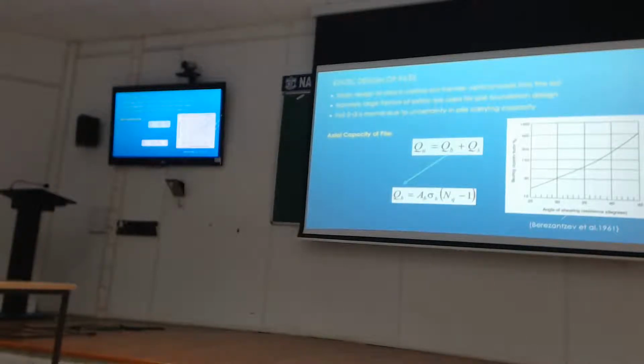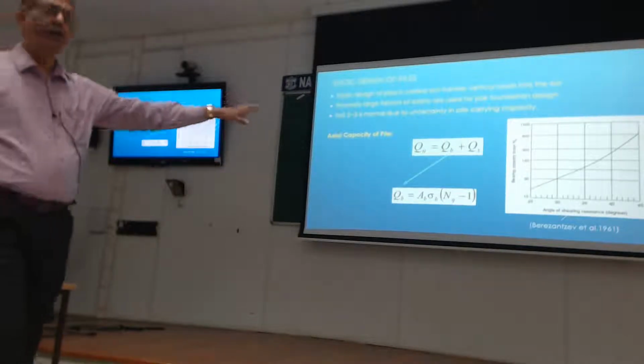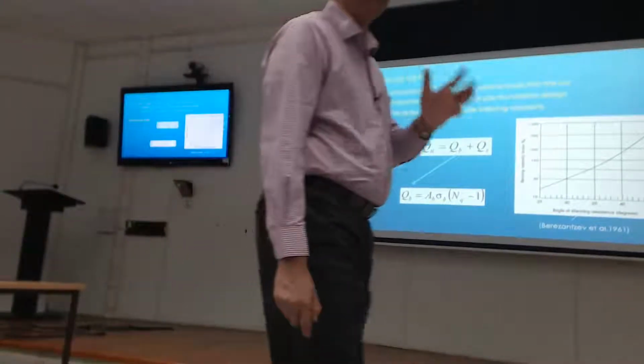And this Nq factor changes dramatically, as you can see, with the friction angle. So if you estimate 35, you get about 60. If you made it about 38, you get about 100. So you can see at least whether this graph is right or not.